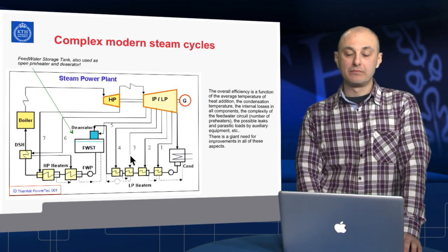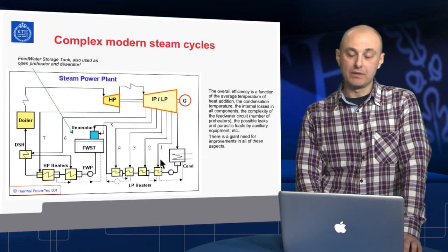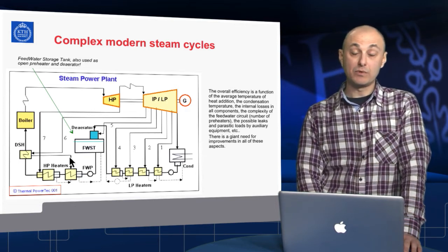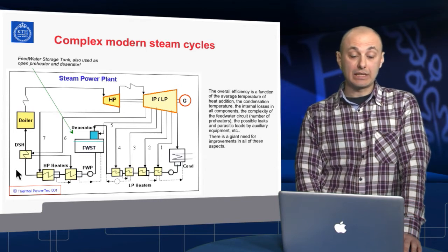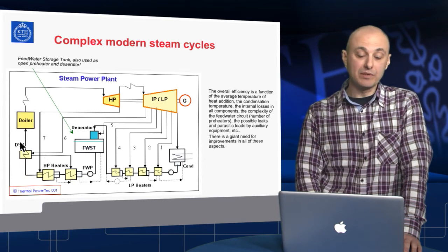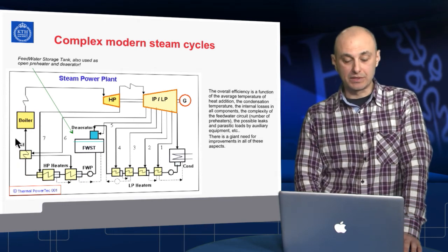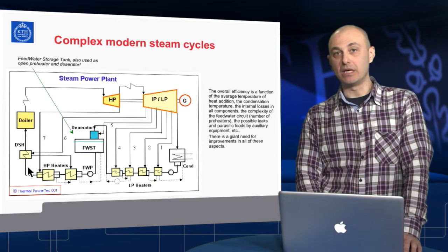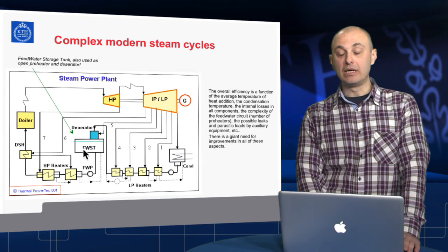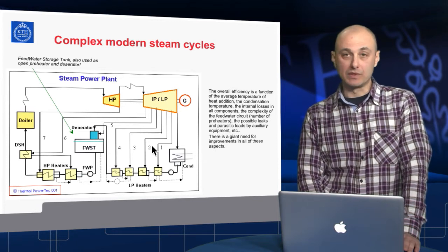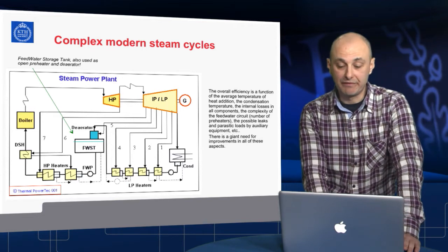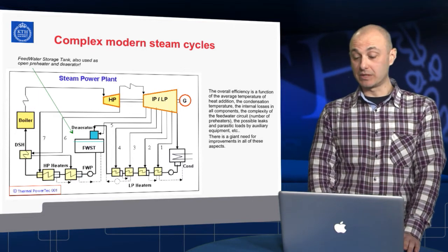Condenser, preheaters, one or many of those, or none in some cases. A feedwater tank, any other kind of heat exchange in order to integrate a bit more of internal regeneration or to take care of certain other thermal leaks and bringing them back into the cycle, and many other auxiliary components that we very often do not show in the simplified drawings and diagrams that we work with.